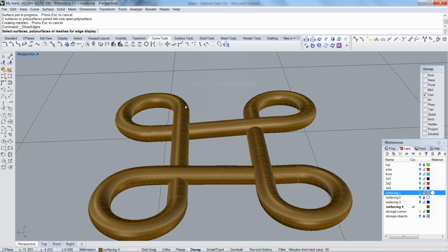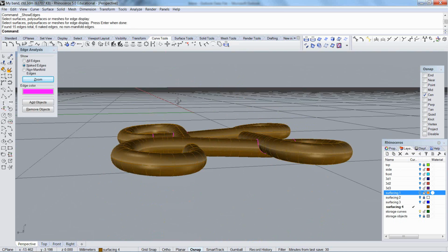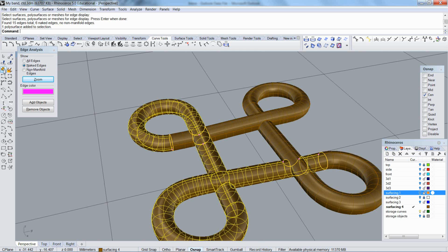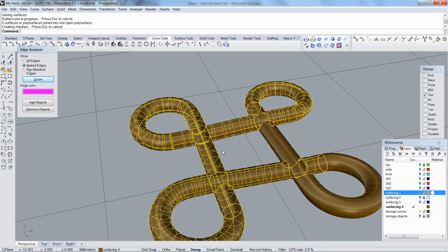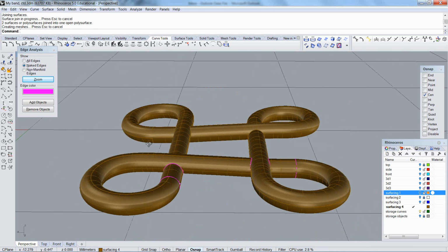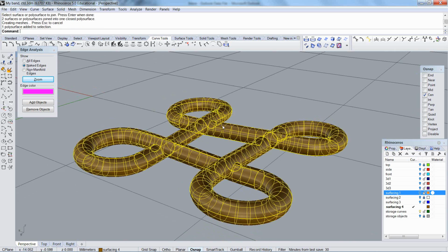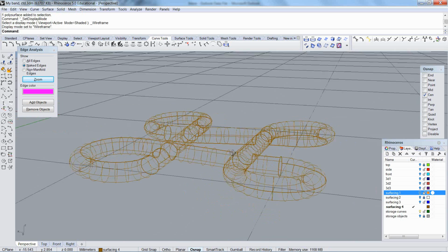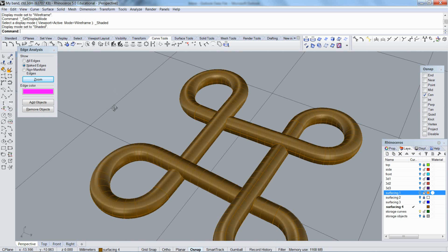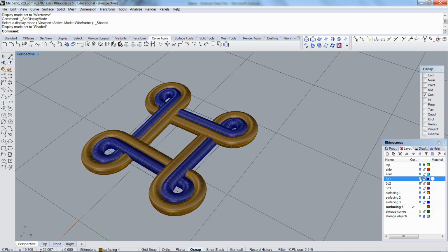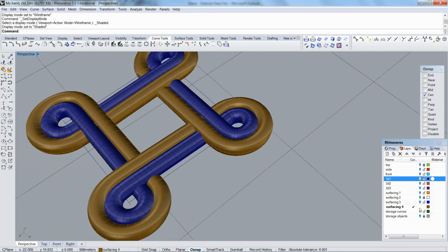Turn on my edges so I can see what I've got. See? It didn't leave an edge naked that time. Join. See? No edges naked where it's joined. Join. And flash. Now it's a solid. No self-intersecting geometry. Okay? This is the problem I face with each one of my patterns. So I'll take care of the next one with less conversation, of course.